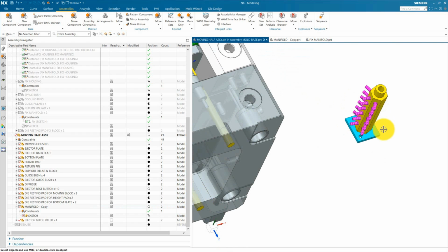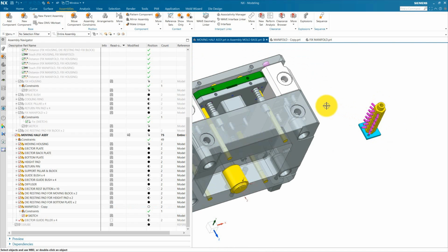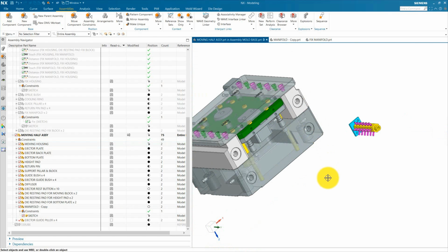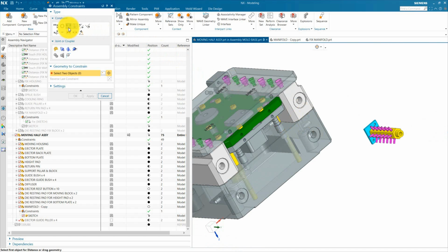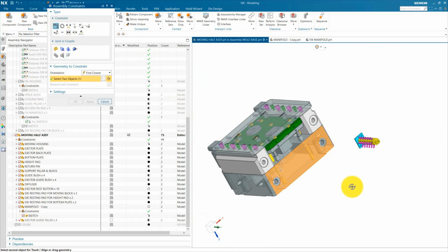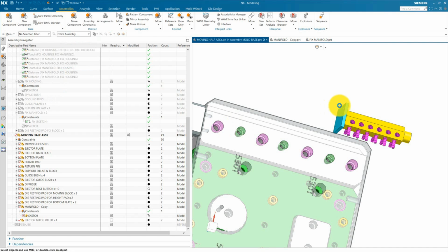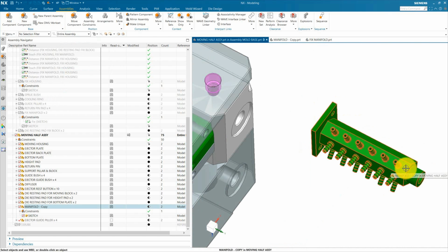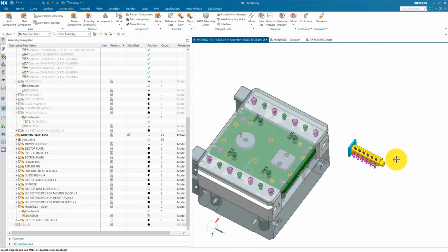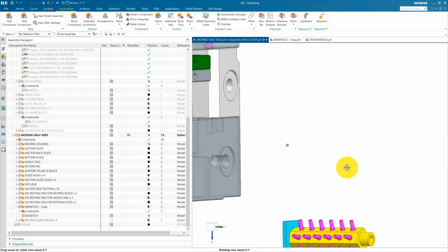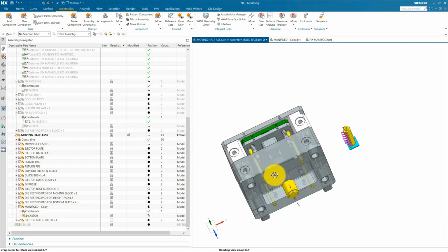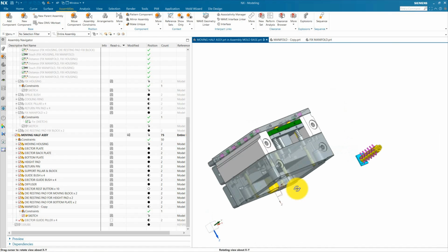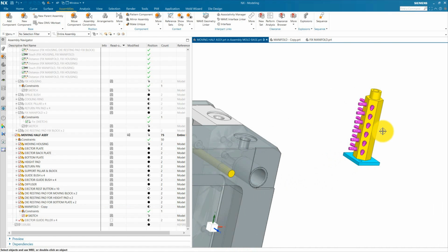I recommend assembling this moving manifold near the bottom face of our moving housing, since most of the cooling pipes come from this side. So we are going to use a touch and align constraint and select this face. You can see the size of the moving manifold is larger than the fixed manifold, and the number of nipples is also increased. It depends on the cooling line number.